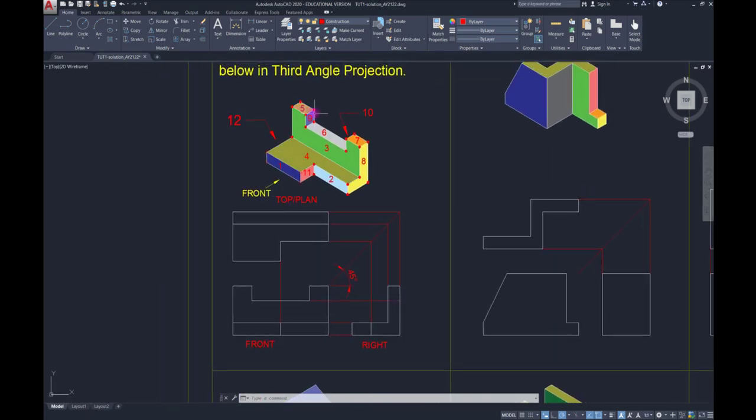Next thing, I need to split them into the respective rectangles. Line. From the front view, I know this is the size. Click on this, push up, click, same thing, spacebar to repeat the last command. Click here, click here, click here. So I can select these two and change them to outline. Escape. Now I double check.